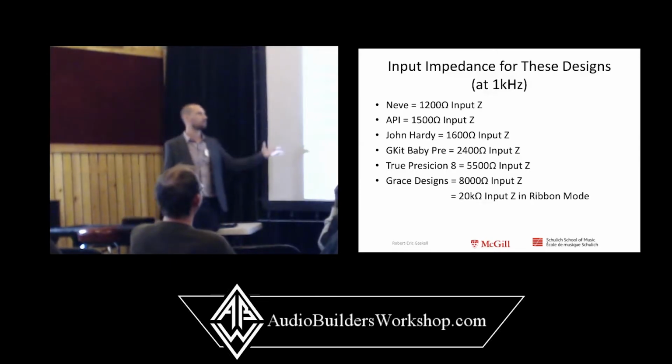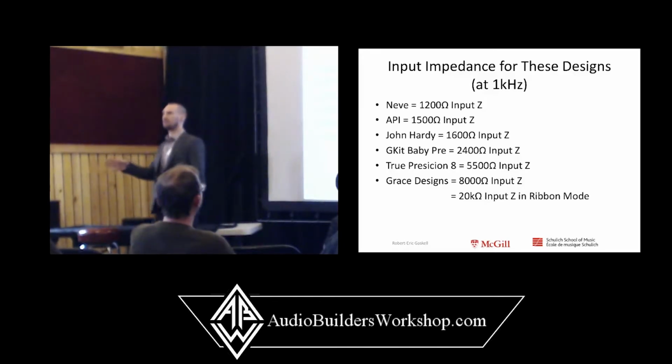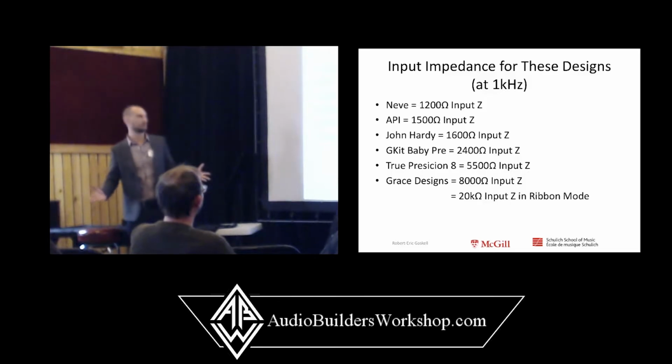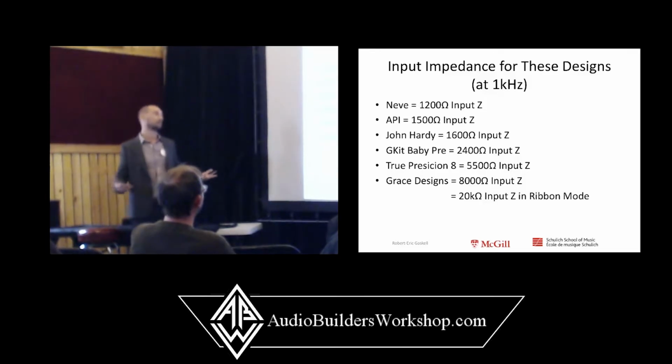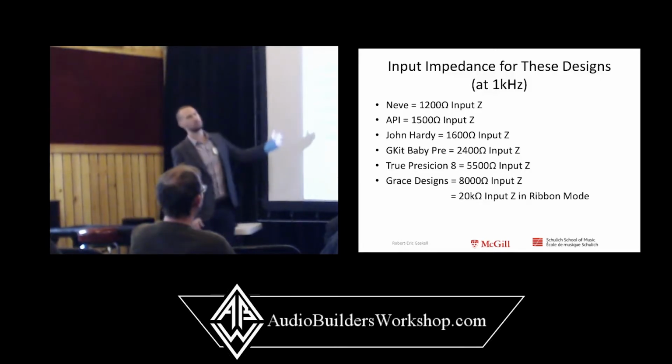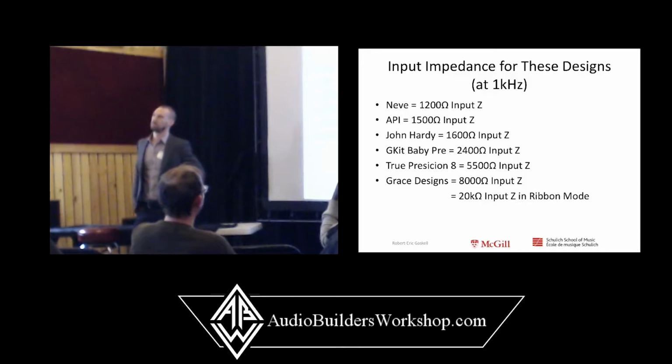But some modern microphone preamplifiers will have much higher input impedances. The True Precision 8, did I say that? Sorry. The True Precision 8 has about 5.5K input impedance. Grace Design, I think I said 6K before. I trust my slide more than I trust my memory. 8K input impedance. So that will change the characteristics of the microphone that you plug into it. Again, Grace's ribbon mode bumps that input impedance up to 20K.